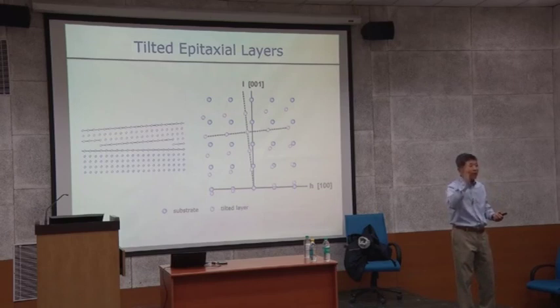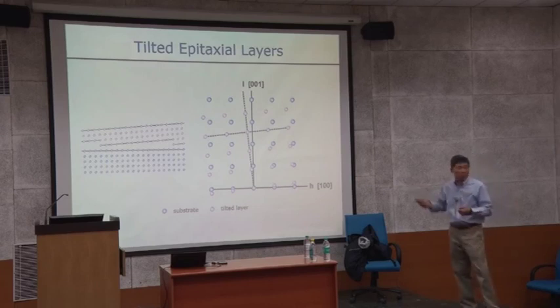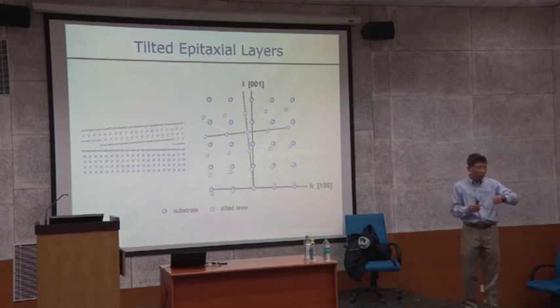But if you go to a high chi angle, you have less resolution of the d-spacing in the H direction. So that's why most people use a 101 or 102 reflection, which is a low index XRD peak with stronger intensity and a more favorable geometry, which means lack of 45 degrees. I'll show you later. I'm going to go to the next level, then we can talk about it.